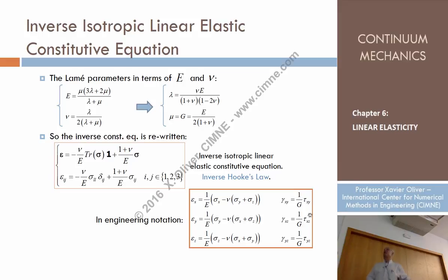So that also indicates why this is called the shear modulus, because the shear stresses are obtained by multiplying this G modulus times the angular strains. Okay? So this is the way that maybe you recognize. You recognize this formula now? Have you ever seen that? This is the formula that comes in many elasticity books. But this formula comes up from all the theory that we have visited so far.